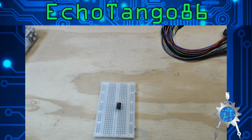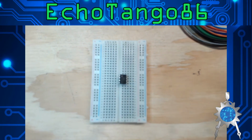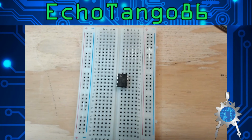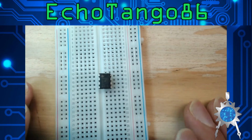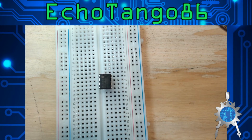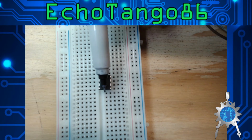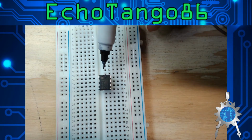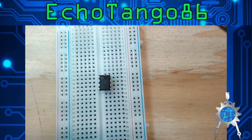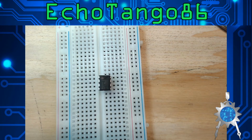There's our 555 chip. It's not very big. So you see it has 4 pins per side. Starting over here, that top pin's 1. It counts down, crosses, comes back up, and then that pin up there is pin 8. So that's how you calculate it. And I don't know if you can tell, but there is a little notch up there that signifies that that's the top. And a little dot. You see that little circle right there? That little circle and notch kind of tells you the orientation of the chip to know whether it's facing straight up or down. So that's that.